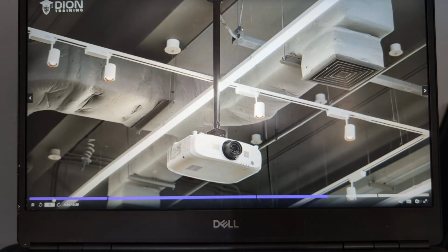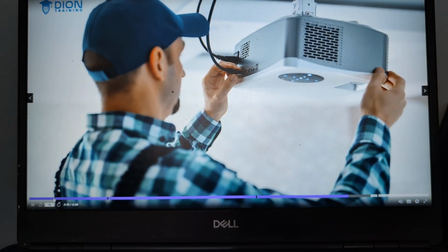But if you have the projector hanging from the ceiling, most of the time, people don't think to actually clean out those air vents on the projector, and this can lead to the projector's fans getting clogged with dirt or dust and making them overheat. So, if you start having a projector that is intermittently shutting down on you for no reason at all, most of the time it's because it's overheating. In these cases, you want to check the projector's fan and make sure it's working, and make sure that its air vents are properly cleaned and clear of any dust or dirt or debris to be able to make sure that the airflow is going through that projector properly and cooling down that system.